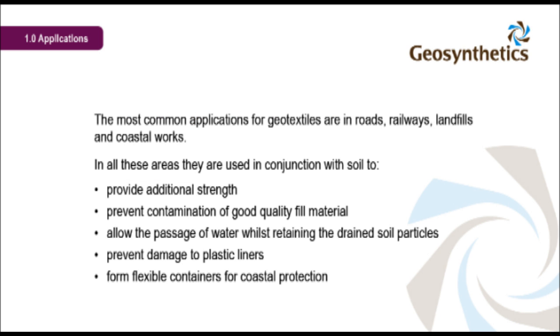The most common applications for geotextiles are in roads, railways, landfills, and coastal works. In all these areas, they are used in conjunction with soil to provide additional strength, prevent contamination of good quality fill material, allow the passage of water whilst retaining the drained soil particles, prevent damage to plastic liners, and form flexible containers for coastal protection.